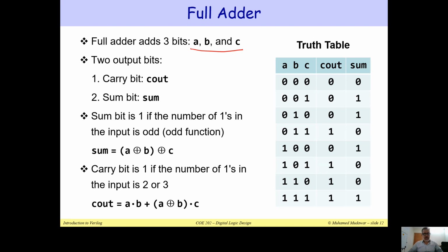That's basically it. So we have 8 entries in this truth table. You can see that we start here at 0, 0, 0, and we end here at 1, 1, 1. We have 2 outputs, like in the case of the half adder. We also have 2 outputs in the case of the full adder: a sum bit and a carry out. So we take it entry by entry. We add 0 plus 0 plus 0. This will give me the sum equal to 0, and there is no carry out. So this is my first entry: sum equal to 0, C out equal to 0.